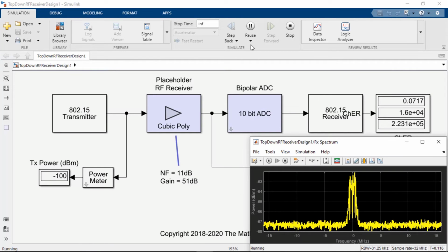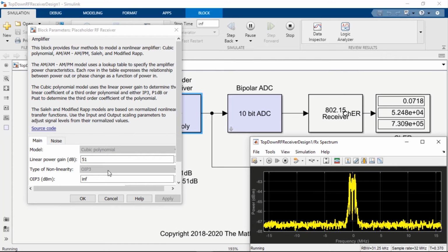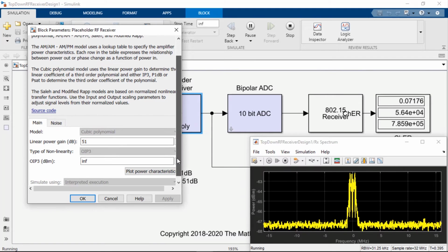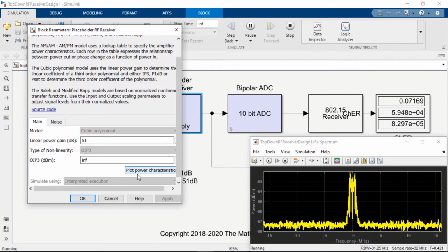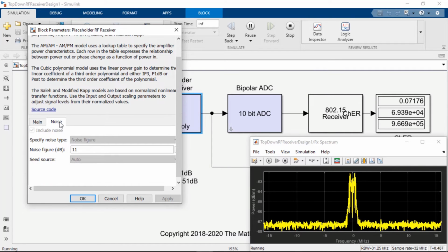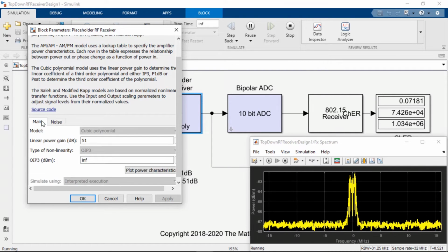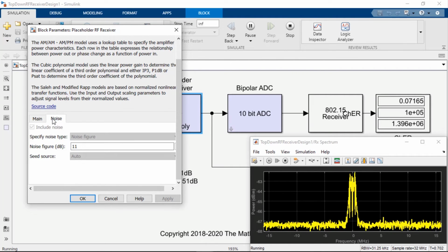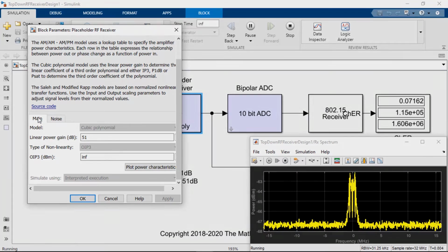We can validate that the link budget analysis accurately predicts the overall system performance, and that with the derived gain and noise figure we can indeed achieve a chip error rate of approximately 7%. The very important questions that we need to answer also in this case are: how do we partition the gain and noise budget across the different components of the receiver? And what about other effects, such as phase noise or nonlinearity or antenna integration? These are exactly the same questions that we had before for the radar receiver.